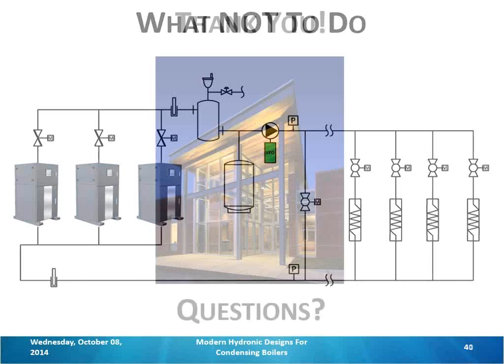If you were to use it modulating, you could, but it sometimes becomes difficult to dial it in because that modulating valve might fight the pressure that the pump is based off of if you're using differential pressure for your VFD. And it's kind of like pulling levers. Your pump is going to ramp up and that valve is going to open, and they're just going to bounce back and forth.